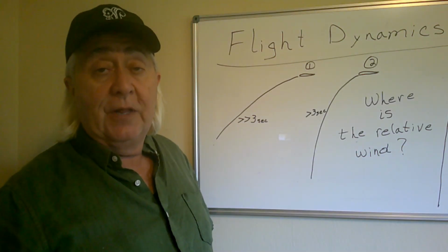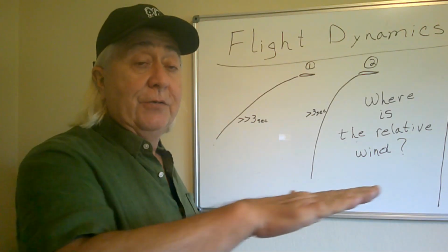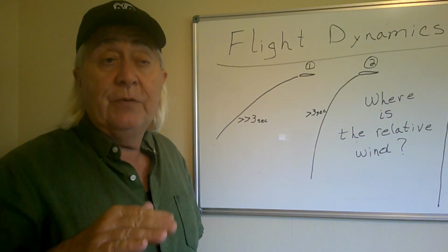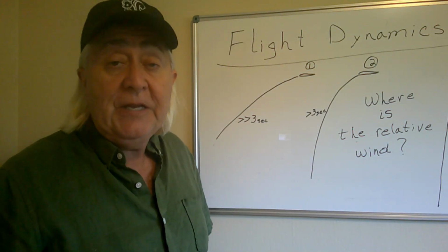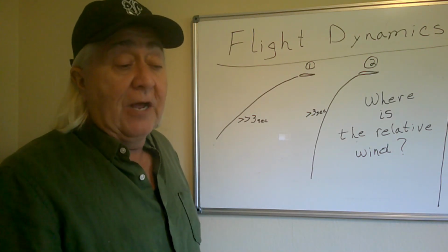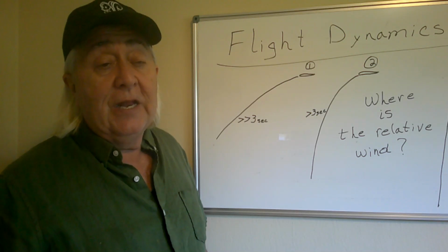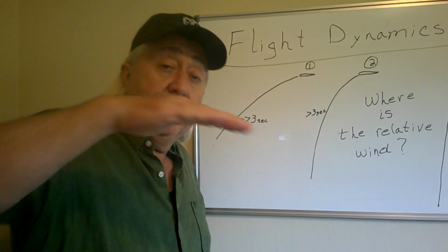So you pull in up elevator. You pull that stick back, pull the elevators up, and get back to a trim speed. Now your trim speed with the flap down and elevons up is different than what it is when you're completely clean configuration. So you put the flaps down a notch. Whether they have notches or not, I don't know, but you go for a setting. You put it down 10 degrees, and the glider starts to descend.